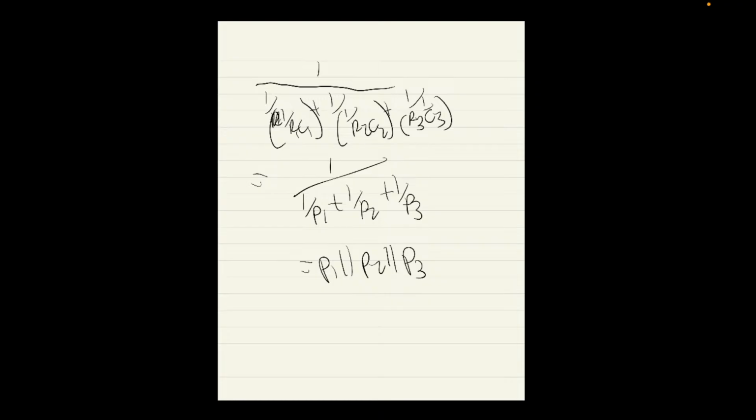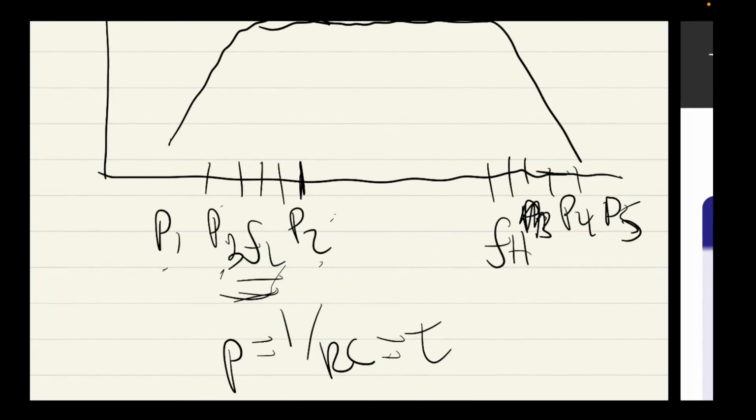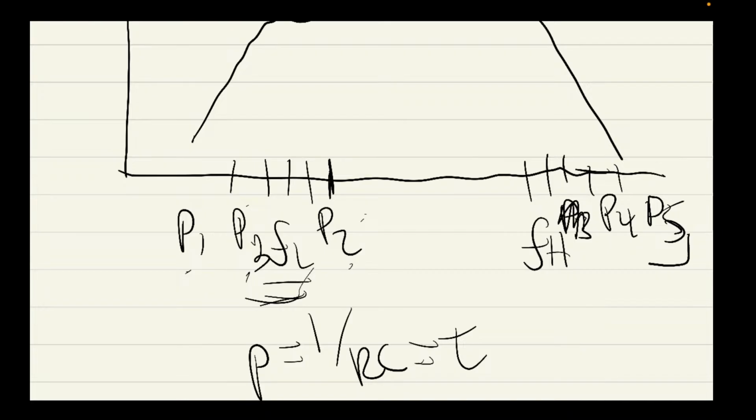And if you think about your resistors, it's sort of an analogous problem. If you take your resistors in parallel, you know that if you have a low resistance in parallel with a very high one, your high one doesn't really matter. You can just assume it's the small one. Well, here, if I'm taking these really high ones right here, and let's just say P5 is much larger than P3.